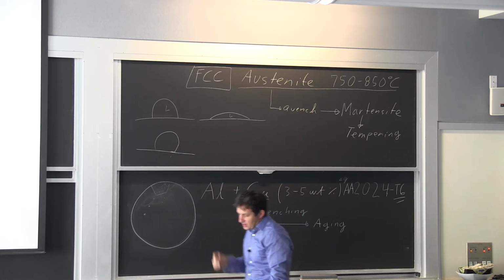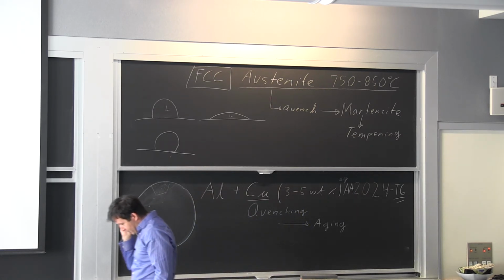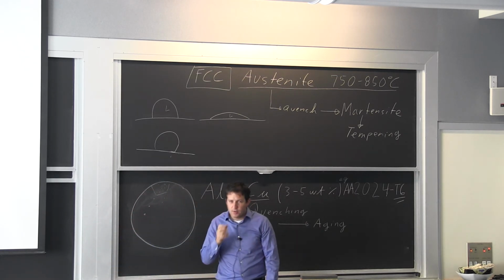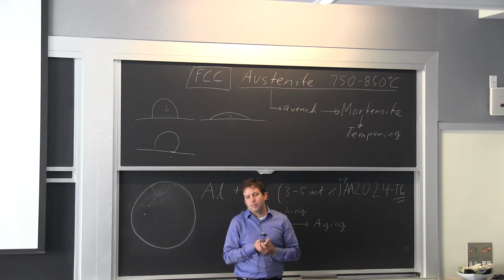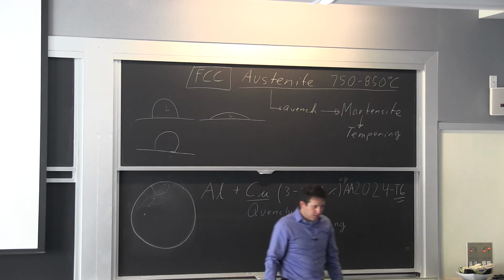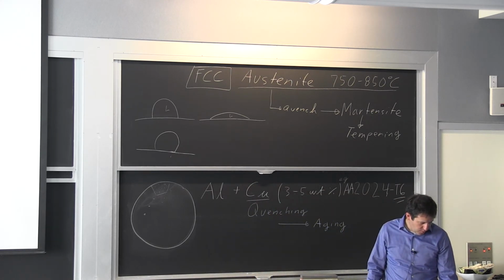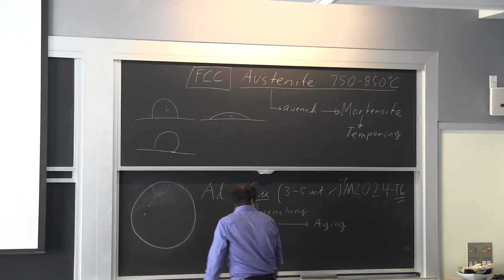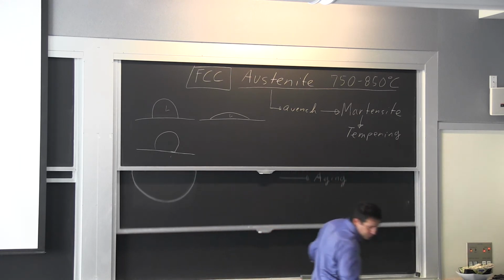Okay. Yes. It's a very good question. If you're at high temperature, you almost need to be at a grain boundary to start, to minimize that critical size. It ends up being, like I've shown on this sketch, that you start from a triple grain boundary. So you already have 3 interfaces to begin with, and you're just sort of eliminating one.